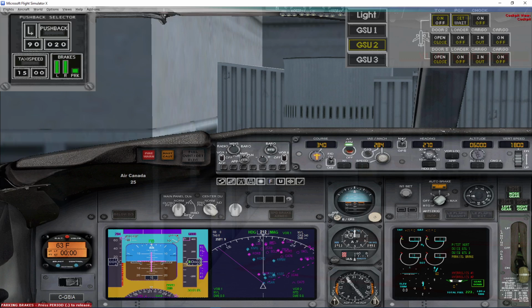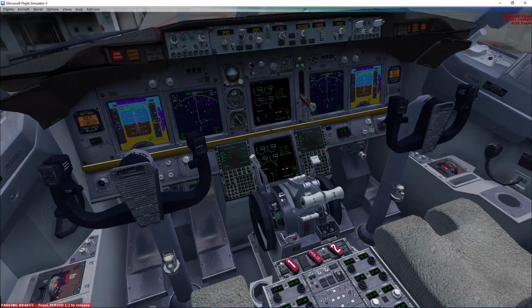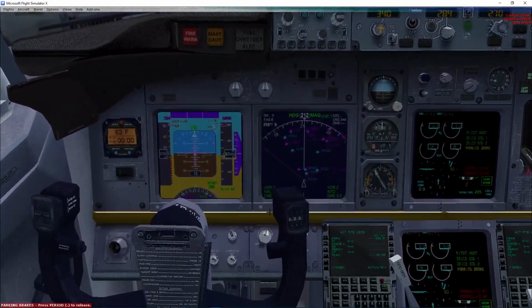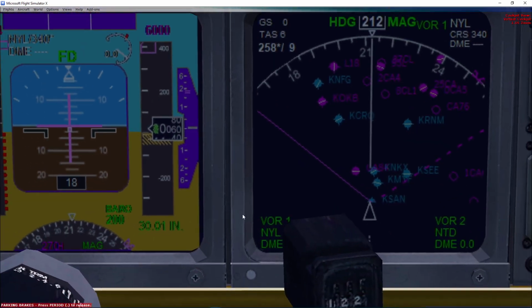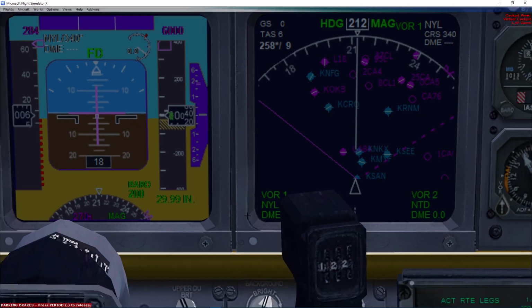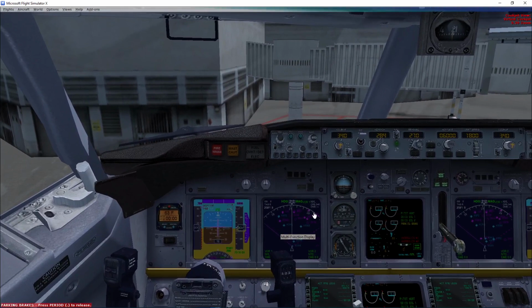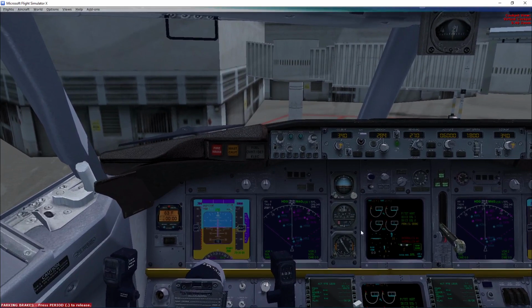We also need to make sure our altimeter is set correct. That's the B key. 40, so we're at 40 feet here. Say we're at Denver, it could be 600 feet. But we gotta set that, it corrects some of the gauges, especially our altitude.